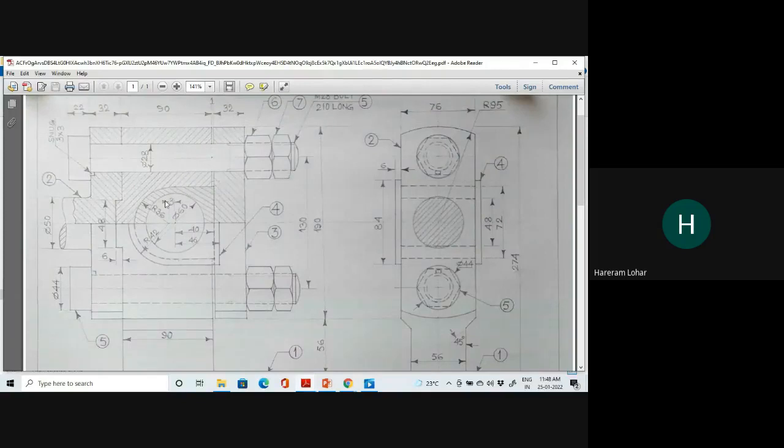And again, when we see the brass here, where the sectional view is there, the collar will not be shown, because it's the half sectional view. The collar will be at the other side, but we know that when we obtain the sectional view, the hidden object is not required to be represented.